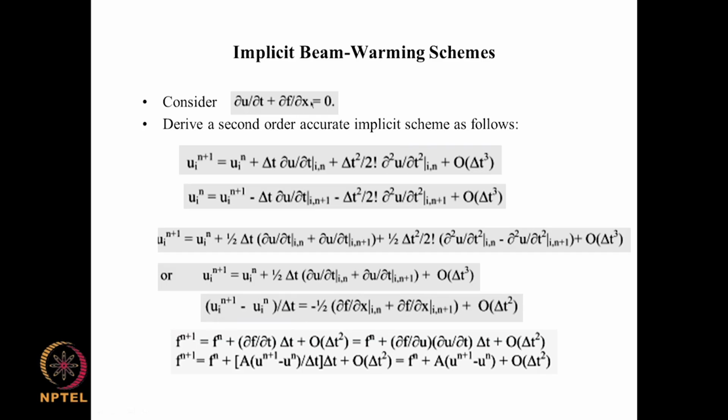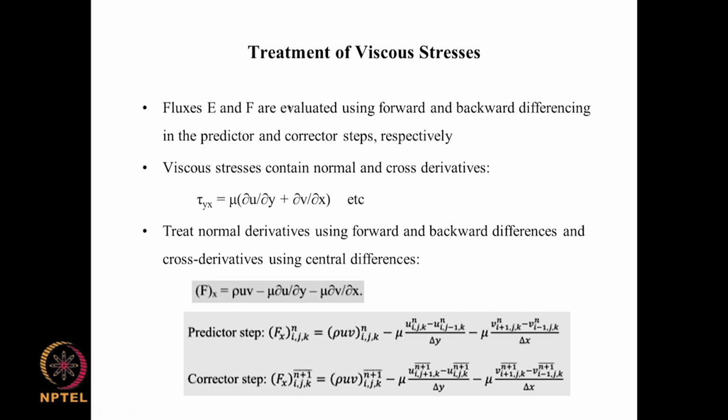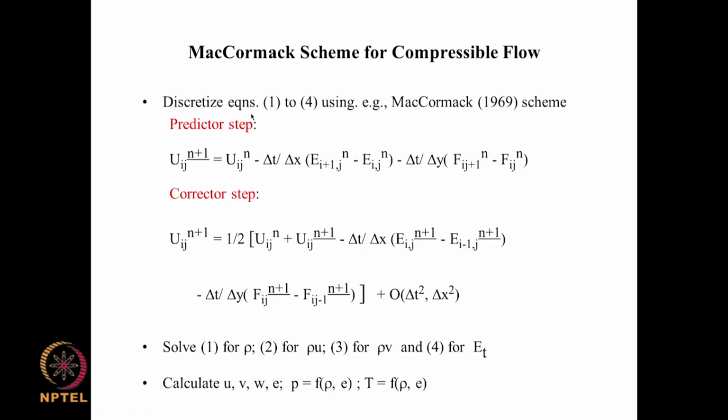So, in this part of the lecture, we will look at the application, or the derivation, of the implicit Beam-Warming method for the simple one dimensional case. And so, we are looking at a one dimensional wave equation type of thing, dou u by dou t plus dou f by dou x equal to 0, where f is u square by 2, it is the usual thing, and we have put it like in the previous cases in terms of the E and F's.